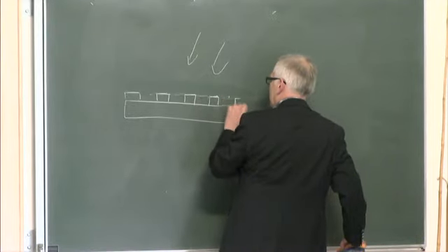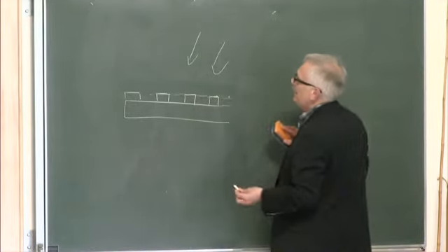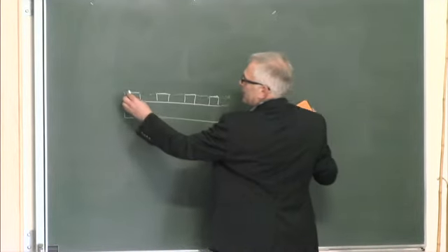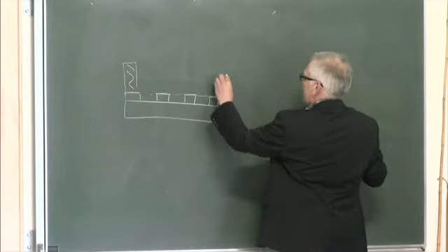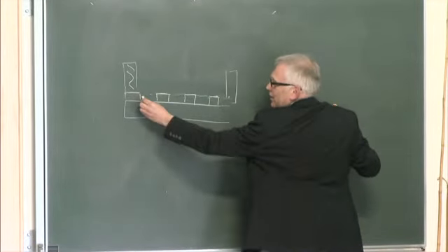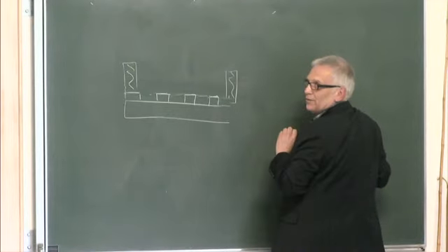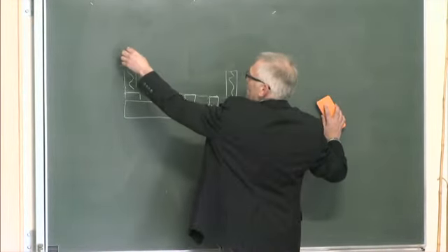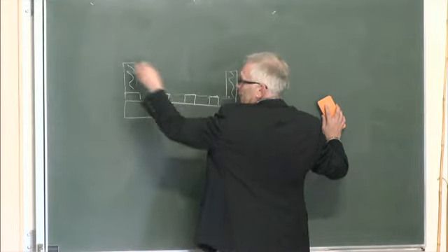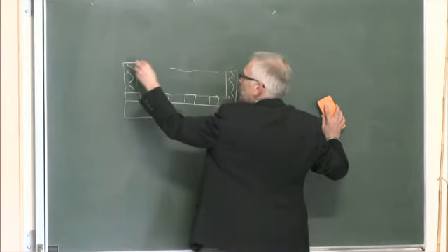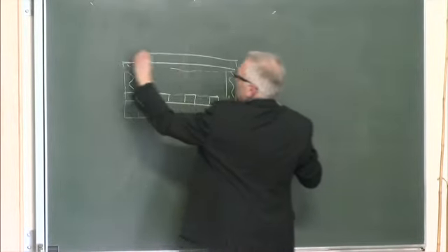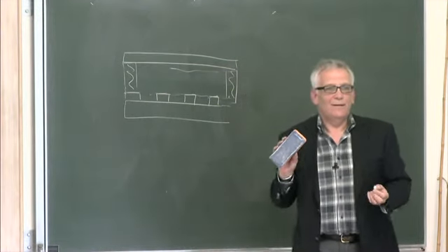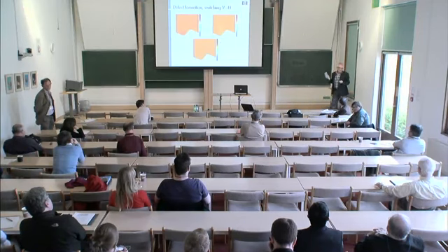So that's the start, and then you need some spacing mechanism over about 80 microns, the sort of size of a pixel. So this obviously isn't to scale, these are about a micron, this is about 80 microns. And then you put liquid crystal in here, and then just squash it down. I think excess liquid crystal gets expelled, and then you've got your cell. That's essentially an outline of the process. There's a bit more subtlety to it.